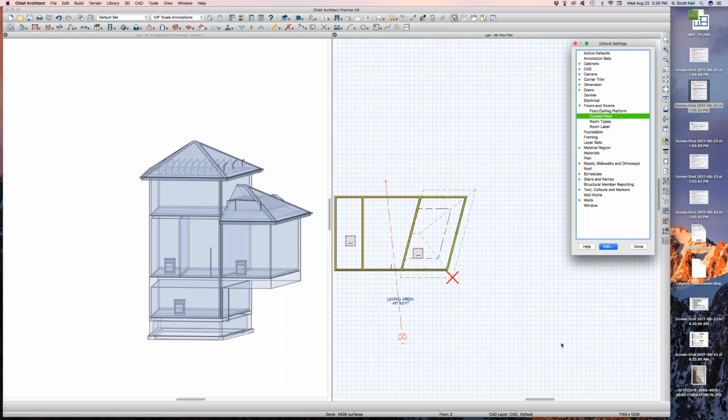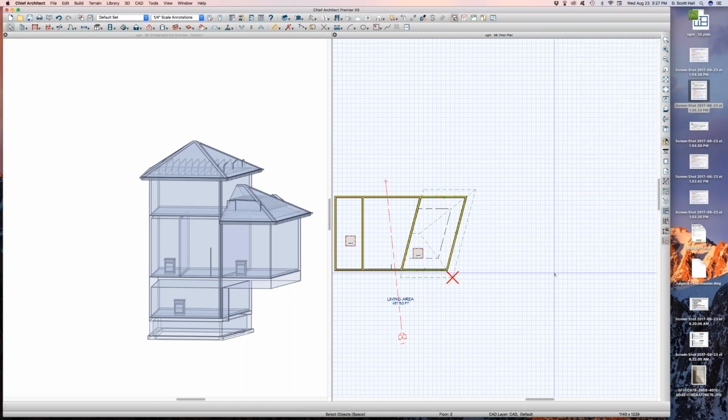Which you have to admit is exactly opposite of how you would think it would operate. Do we agree about that? Logically, it should go the other way because you build from the bottom up. Except that the floor level should take precedence, I think. The floor level is more important than the ceiling underneath. I know what you guys are saying. It makes sense because we were building up, but I think Glenn's right. Let's say you were going from a dimensional lumber size to a truss floor system. You're not going to affect the floor beneath you. You're going to add height to the structure. Yep.